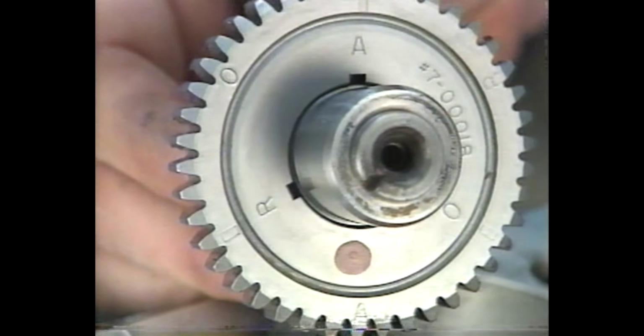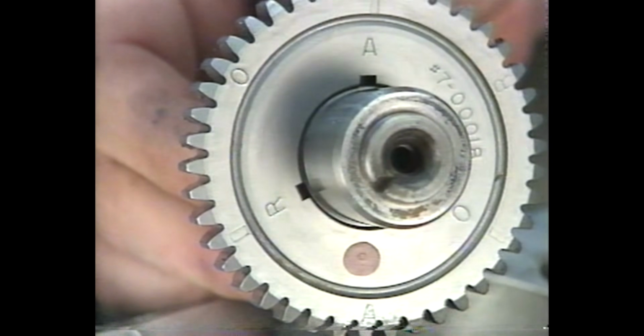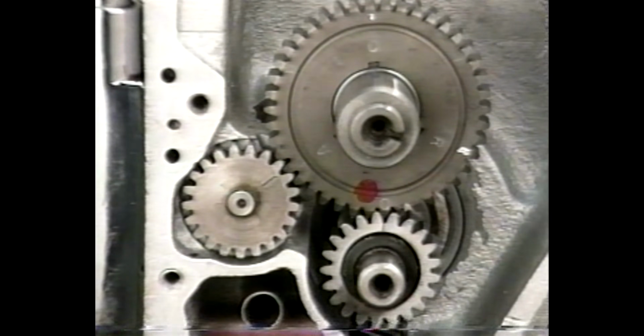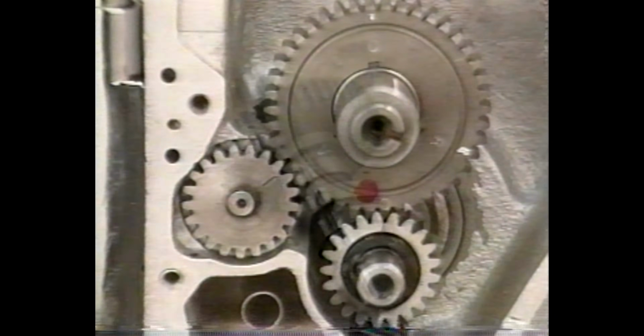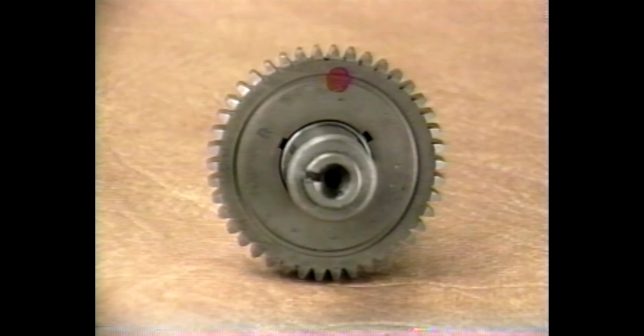Not all cams are designed to provide a continuous range of timing positions. For those who want an easily set but limited choice of timing changes, Crane Cams has developed the High Rollers series of camshafts. These camshafts, which have multi-index cam drive gears, are designed to quickly and accurately advance or retard our valve timing